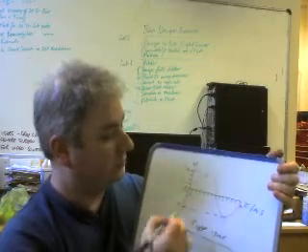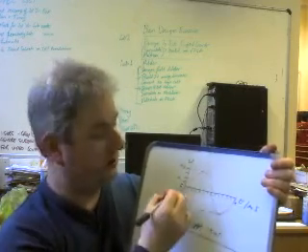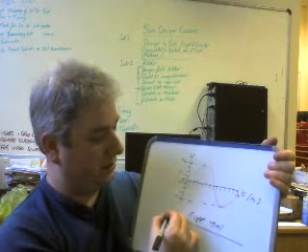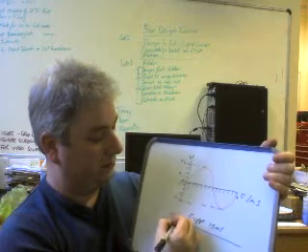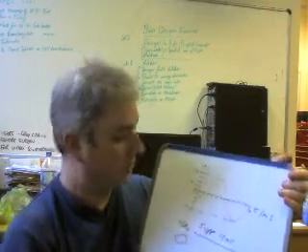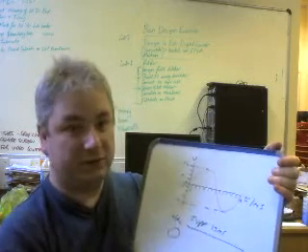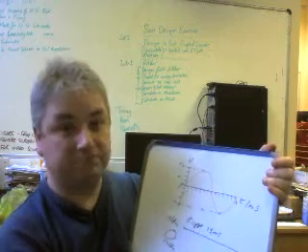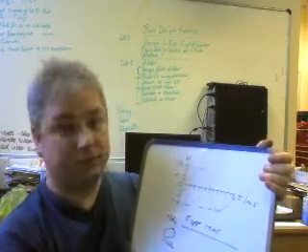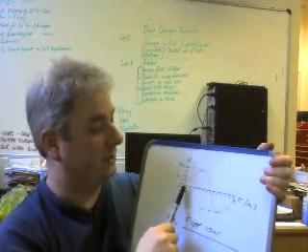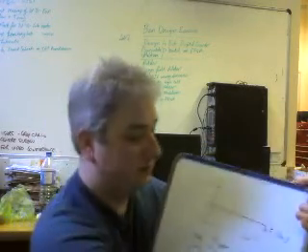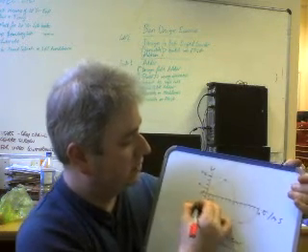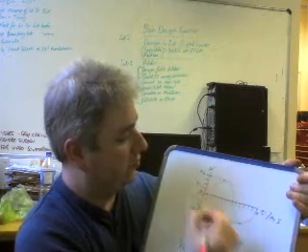Now, on this graph, like I said, we've got linear intervals. On an oscilloscope, we have a nice knob called volts per division. Each of these divisions is 1 volt, so on the oscilloscope this would have been set to 1 volt per division. Time, these are all in milliseconds. Each division is represented by 1 millisecond. So each one of these is 1 millisecond, and each one of these was 1 volt.